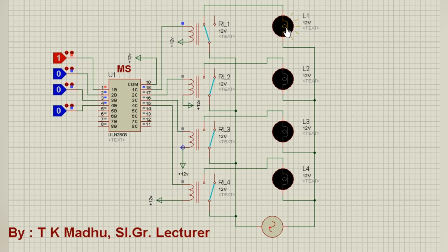So in place of this, we can connect an AC or any load, depending on the load requirement; you have to choose the relay specification, and we can connect any kind of 230 volt load. Again by clicking on this, it is off. Again clicking on this, you can see the bulb glowing, and the animation of the bulb glowing is also represented. Similarly, if I want to drive one more channel, one more load, I will make this high. Now you can see this load is on. Similarly, the third one, fourth one. So now all are on.